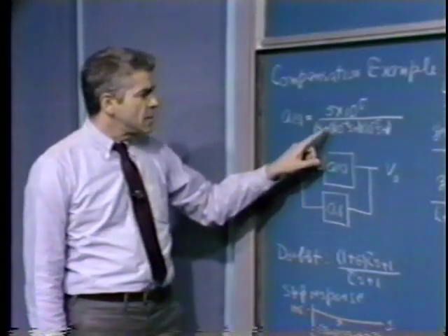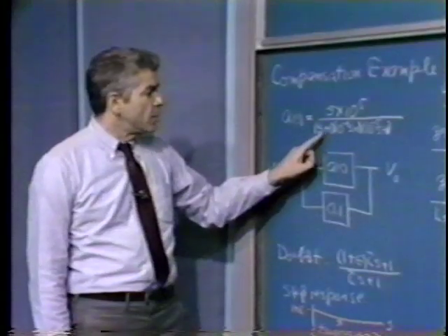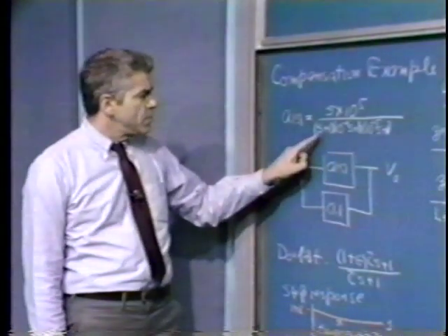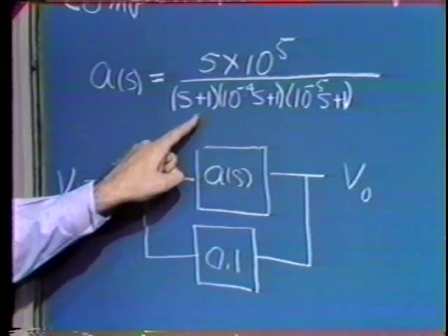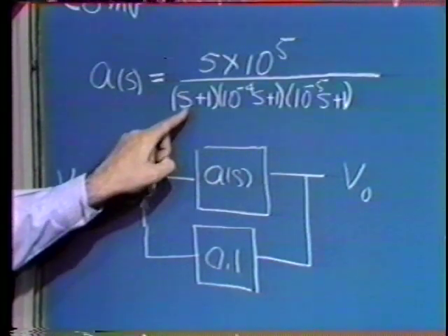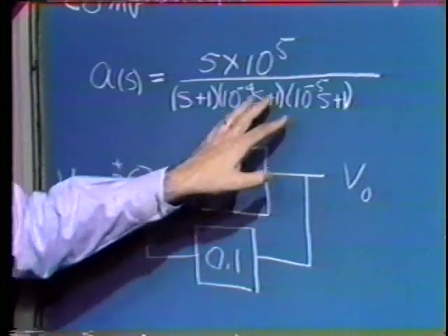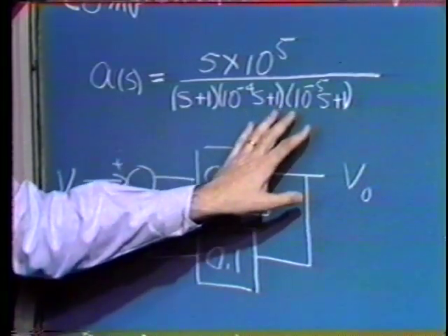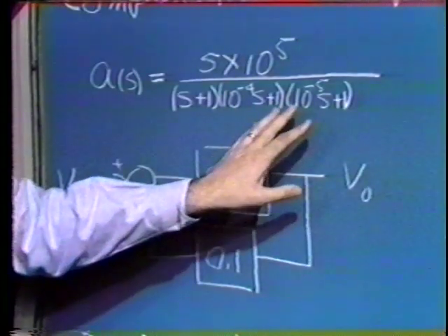You see, when you design this sort of an amplifier, or in fact when you design many mechanical systems, servo mechanisms, you try to dominate the loop transmission with a single low frequency pole. We've looked at that method of stabilizing a feedback system before. And so many, many systems of interest have a dominant pole. However, there's then something at high frequencies that comes in that begins to deteriorate the system, and in particular gives you additional negative phase shift.